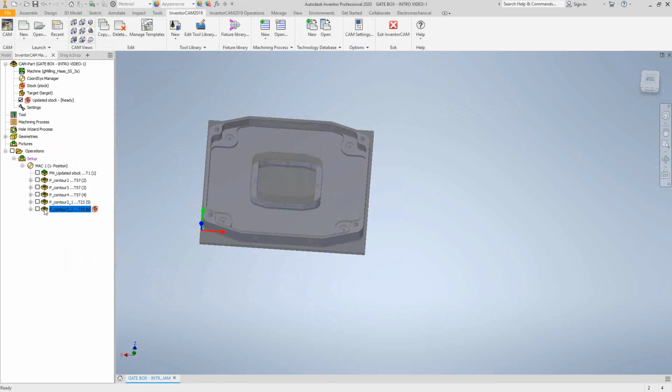So basically, the pocketing toolpath does any cavity or any step that you see. You can do the rest operation to step down your tool. You can keep doing rest operations as much as you need to keep stepping down the tool to get tighter and tighter into the geometry. There's an auto gouge checking in there, as you saw, so it can eliminate any kind of gouging with those steps. So you can freely choose your chains or your faces and get them to generate the pocketing toolpath you're looking for.